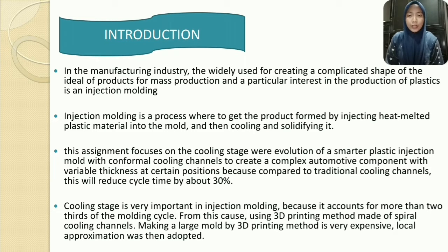Injection molding has 6 major steps, which are clamping, injection, dwelling, cooling, mold opening, and the last step is removal of the product.